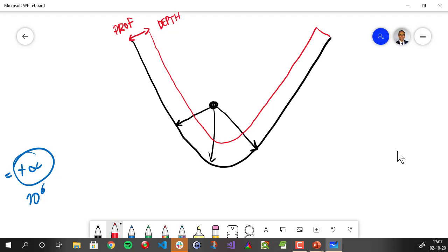You know that if the node lies into this area, this red area, there is only one projection. So it means that here, well, you don't have any, the projection is here. Here, the projection is here, so everything is okay. So this parameter is important to solve these multi-projection problems. But you need to give a value to that number. So this is a numerical parameter that is left to you.